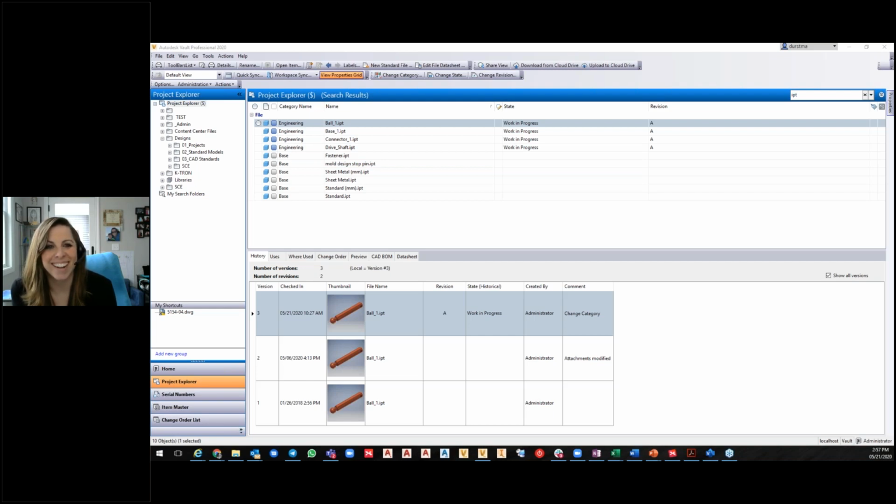Okay, so the question is, I've had it happen no matter if I'm using regular AutoCAD, Electrical, P&ID, Architecture. It revolves around the basic commands like attribute requisition. You have to change it from 0 to 1, and then you close the drawing, open it back up, and have to reset that setting back so that the attribute window actually shows up when you insert a block, or the file dialog box disappears and you have to reset that because it randomly wants to disappear. Start mode randomly wants to start back up after you've turned it off. Some of those simple commands that are built into AutoCAD, for some reason randomly just turn on and off.